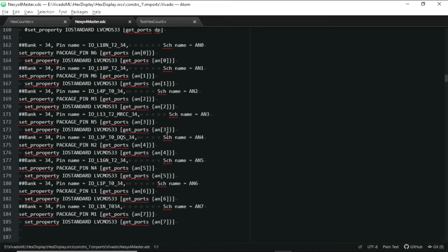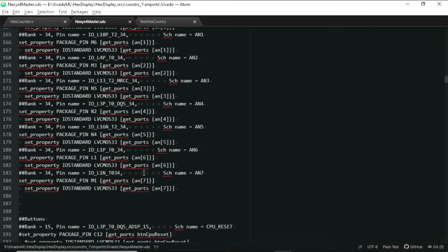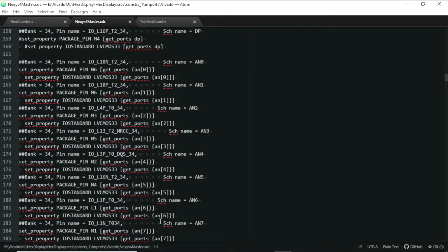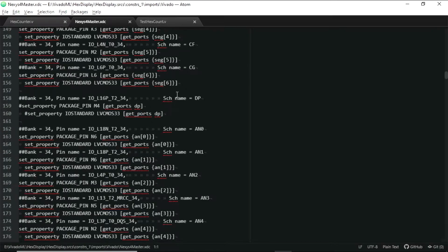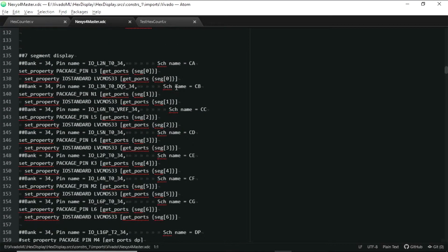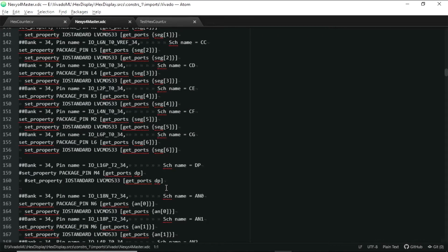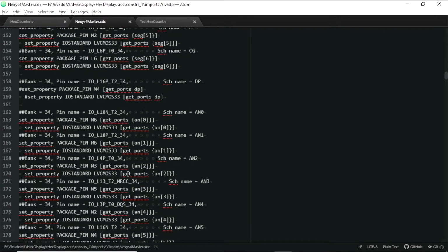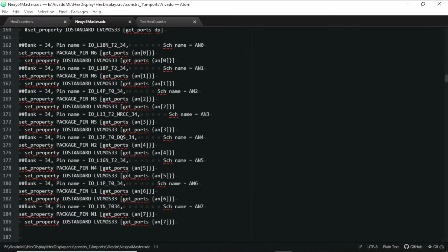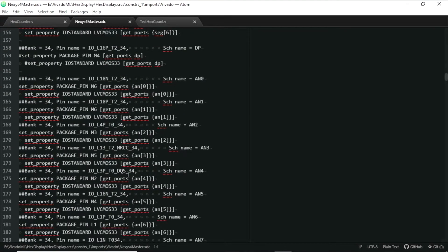Yeah. And so this is the numbers 0 through 7 in the code, and I'm just lighting up each of the 8 digits one at a time with a common anode for that particular 7-segment display. And these are the actual segments. So we have 0 through 6, 7 segments, and a decimal point, which we're not using. And we are using all 8 digits of the display.